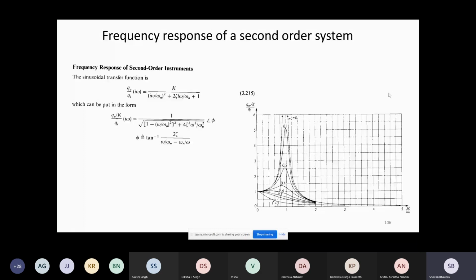So it will be easier if you know the omega versus gain and omega versus phase plot. So easily you can calculate, you know how much input you are giving, what is its omega, and then quickly from the table or from the graph you can see the output phase and output amplitude, and then quickly you can calculate what will be the output.